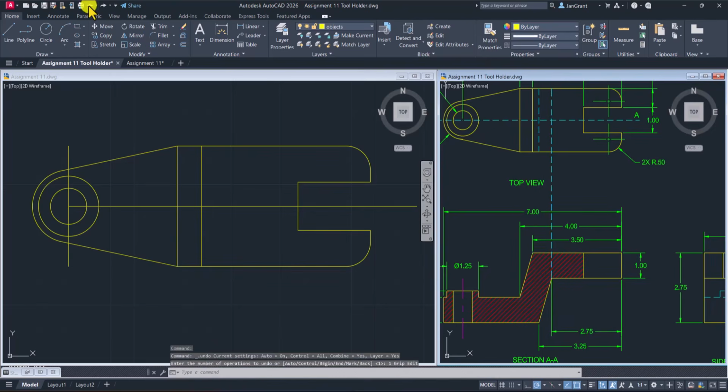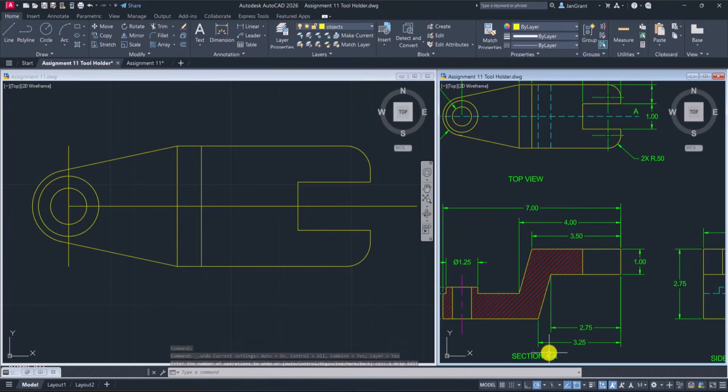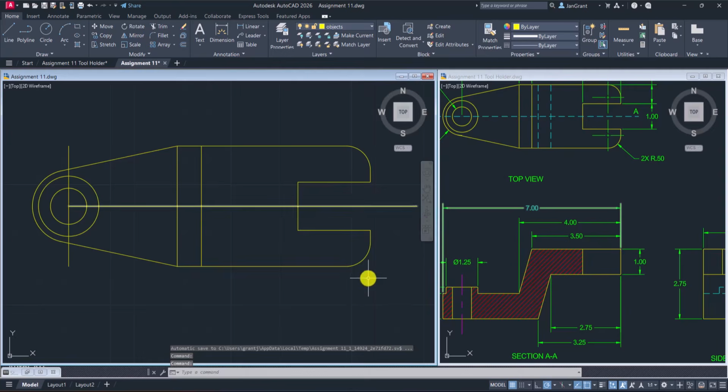So when we're drawing these hidden lines, we can use these dimensions down here in the section for those offsets. One is 2.75 and the other is 3.25. Now, we ended up with just these small pieces down here. So it's okay. We'll just use this small straight piece and then we'll stretch it and we'll move it to the right layer. Now, some of you that use tracking, you know that there's a different way of doing everything, right?